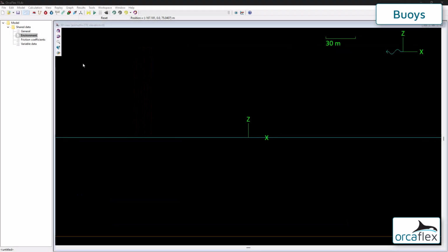We will now go through the process of building a model which compares the behaviour of the different types of buoy in a payload lowering scenario. The arrangement comprises a payload slung from a crane wire using two bridles. These bridles have differing lengths in order to demonstrate the differences in a model with and without rotations allowed, and we will build the arrangement with three different buoy types, allowing us to directly compare their responses as the payload passes through the water.